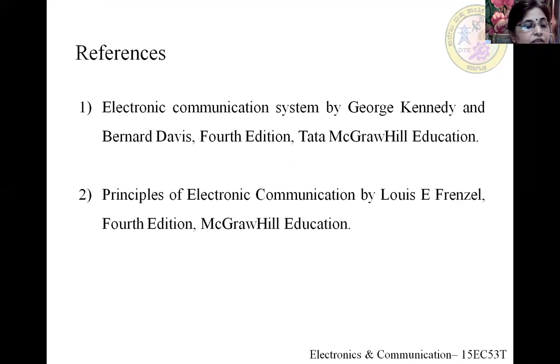Another thing I want to say is that noise also affects the maximum power range, since it determines the minimum power that the receiver can handle. The other factors that should be taken into account are system losses, antenna imperfection, receiver non-linearities, etc. The maximum practical range value varies from 10 to 100% of the theoretical value.